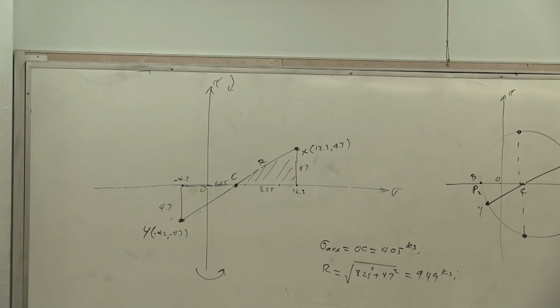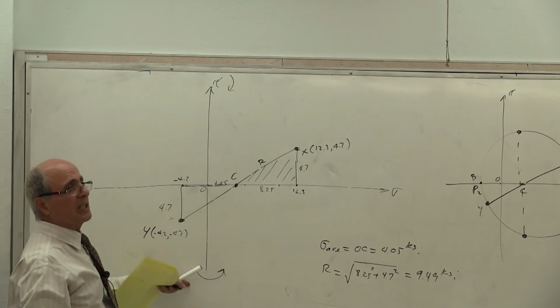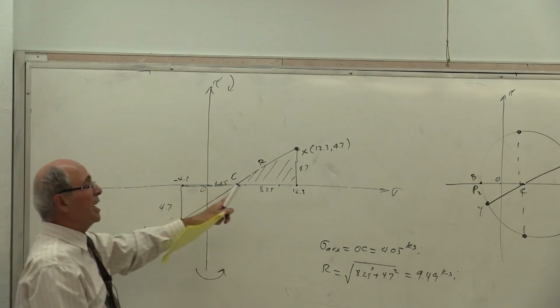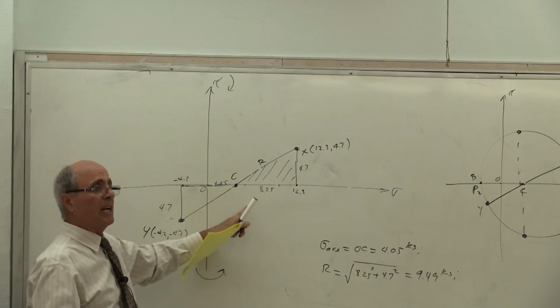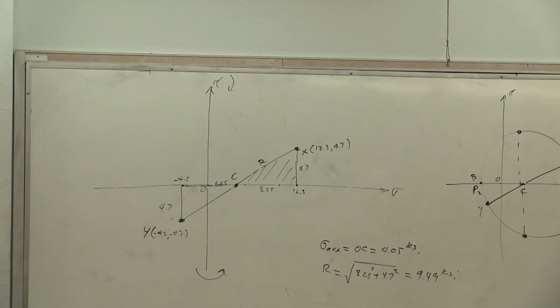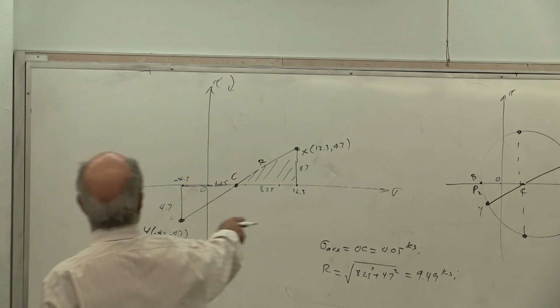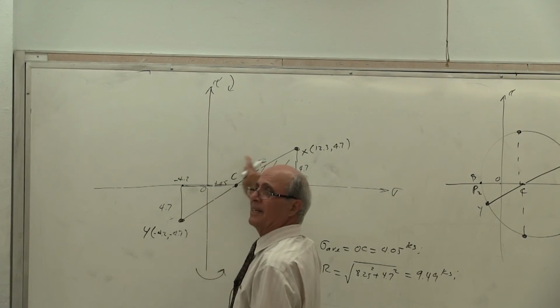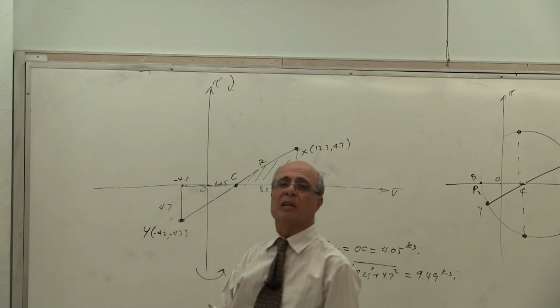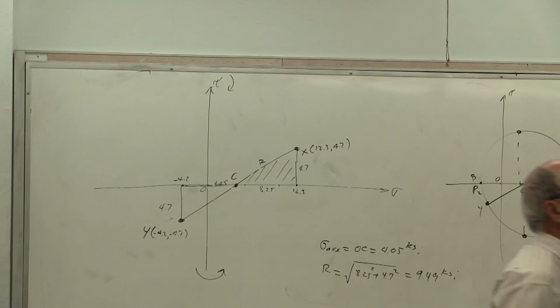What's that angle? Why? Because of the change of the sign that the Mohr circle did. This was a half circle like that. He opened it up. Therefore, write it down in your note if you forgot: every angle on the circle is twice as much as on the real structure. Notice X and Y there are how many degrees? Everybody see that? They are at 90 degrees. The representation of them here is opened up. Actually, X and Y like that, it was opened up because of this. I will explain that to you later if you want to. Is that correct or not?